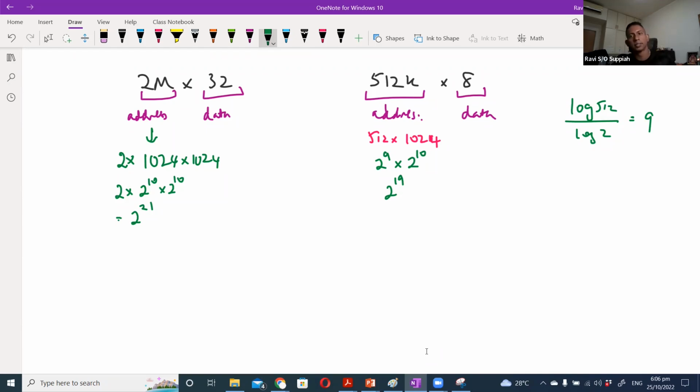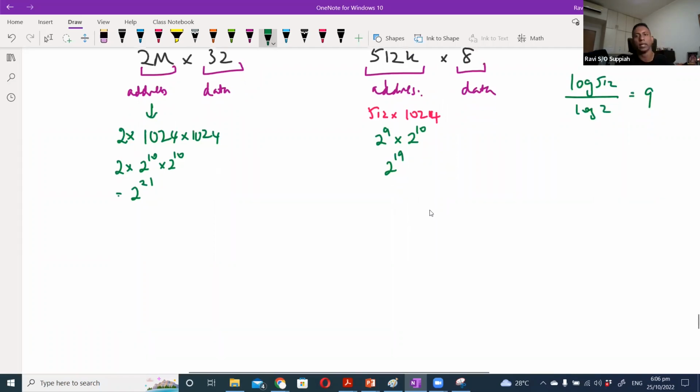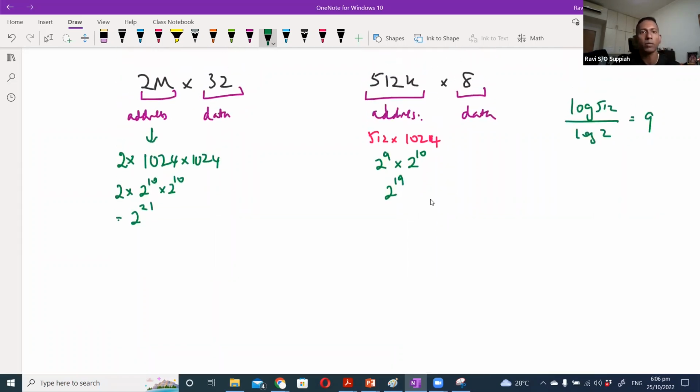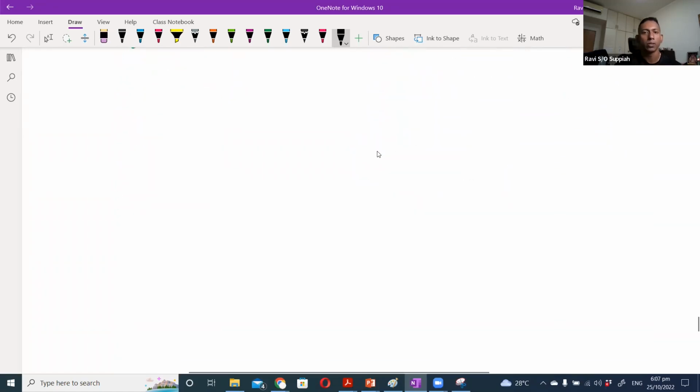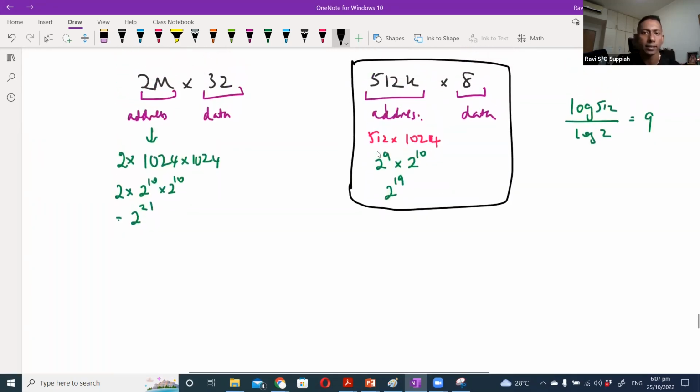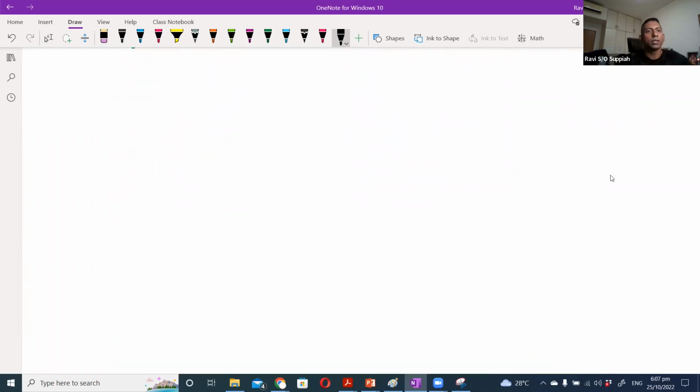Okay, now let's do it step by step and see how it will look when I deal with just one of these chips, and I build my system up from that. I know that I need 19 address lines. Correct, I need 19 address lines to address this entire 512K location. So let's do that first.